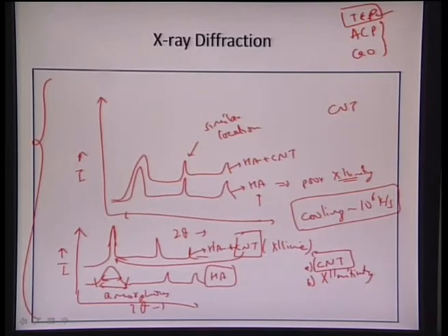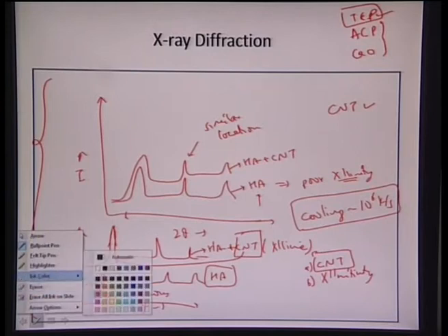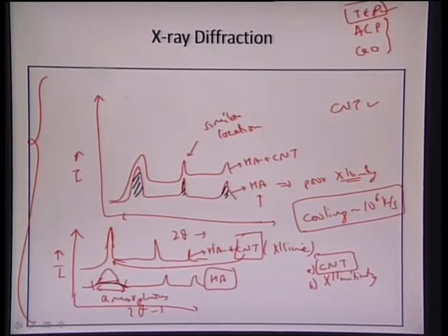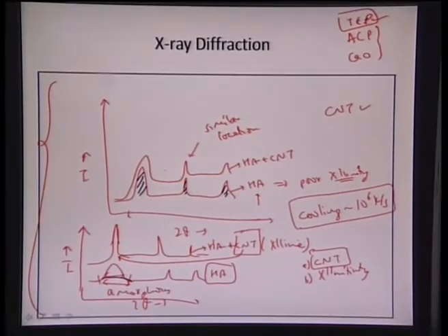Ideally, the crystallinity which is being induced can be calculated by the area under the particular peaks. The area under this particular peak can provide us the overall content of the crystalline nature. If we take the peaks which are much more amorphous, there will be a broadening of the peak.